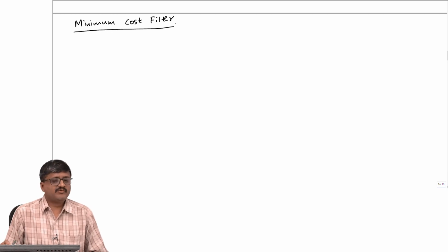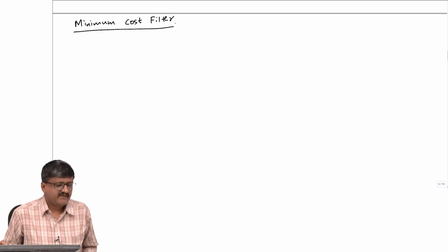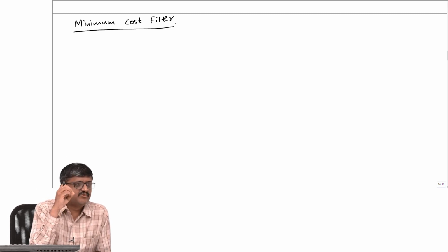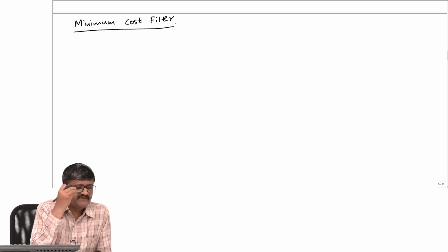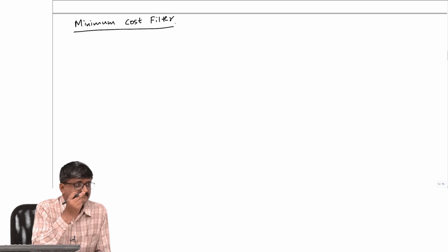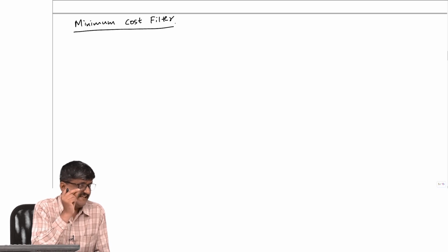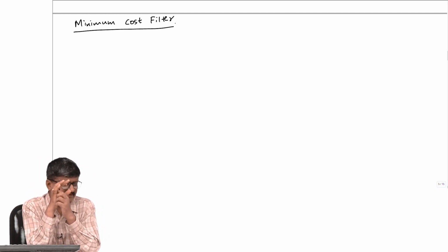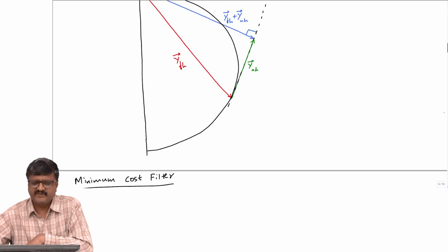Now, when it comes to the filter, what are the frequencies that will flow through the filter? What is the frequency of the currents that will flow through the filter? It is designed for a particular harmonic frequency, IH will flow, then any other current will flow. Actually, it is not IH, please note, we have used a different notation. One has to be careful.